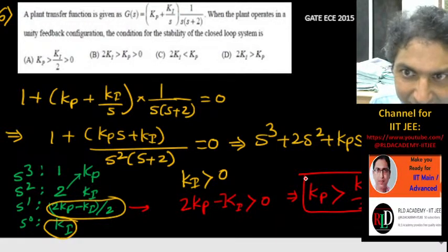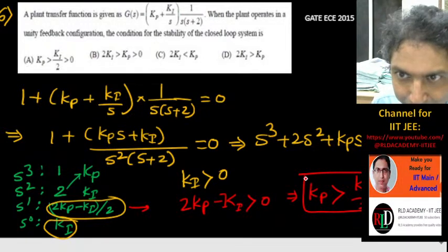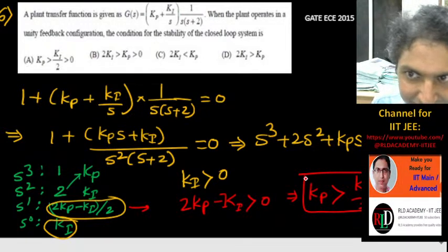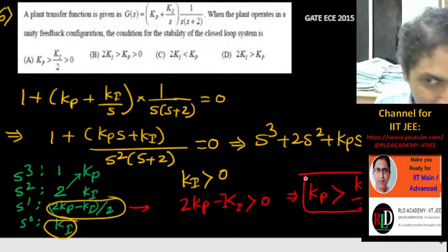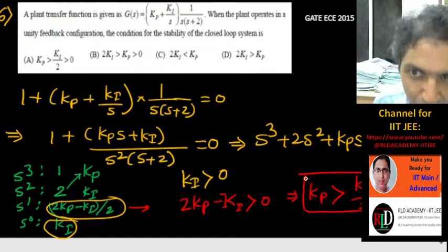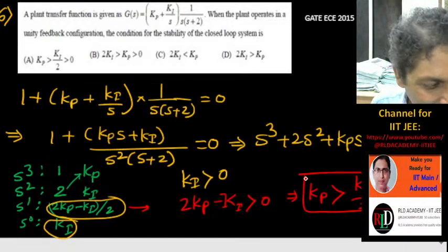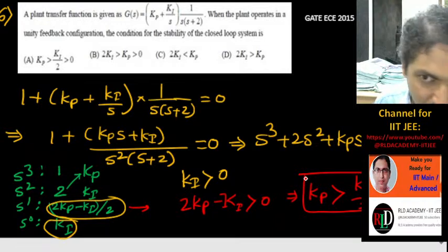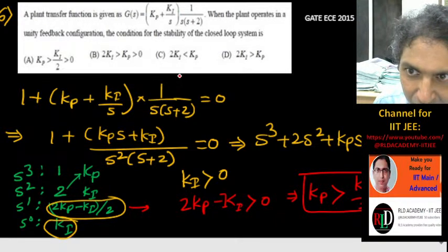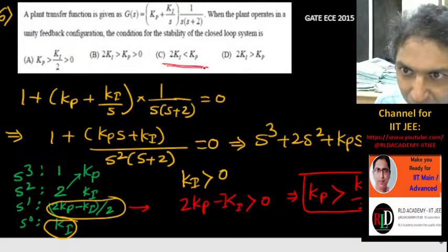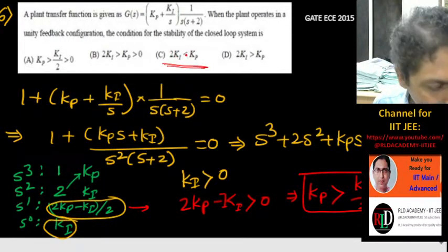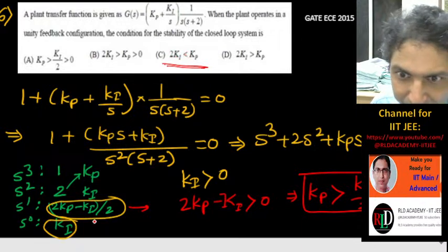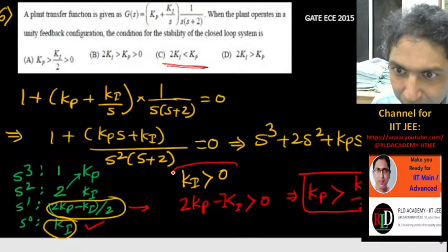Yes, C is also correct, partially correct. 2 Ki is less than Kp, but it is nothing said whether Ki is more than 0. Okay, so you need to include that also. Have you got these things? So C is not perfect because it is not said about their own values. It could be negative or not. So already we have seen that Ki should be positive, that we should make sure.